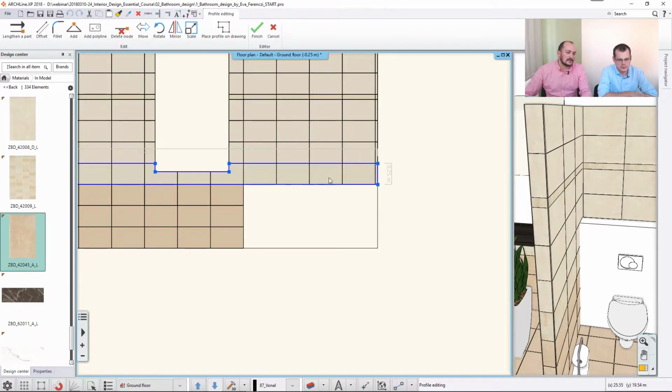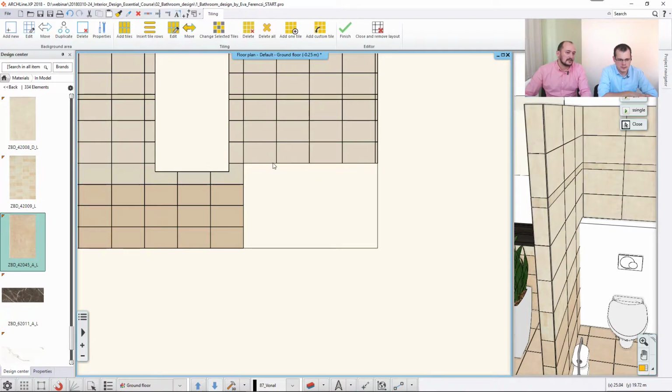Let's repeat that. I click there, I click on the edge, I select offset, I move it back the way I want, I hit enter, I click finish, and then the software finishes that. There is also an area where I don't want to completely remove the whole thing. I just would like to remove this tiny part here.